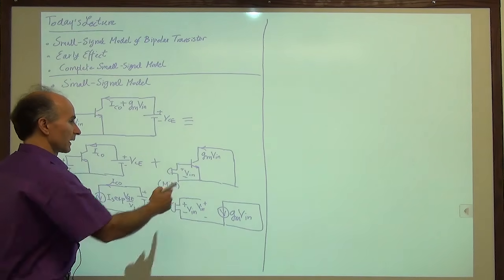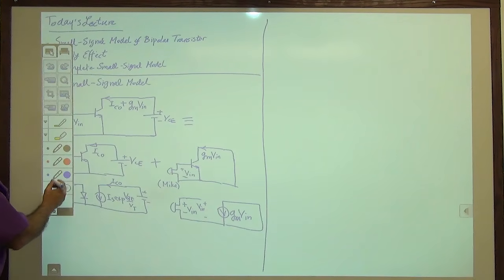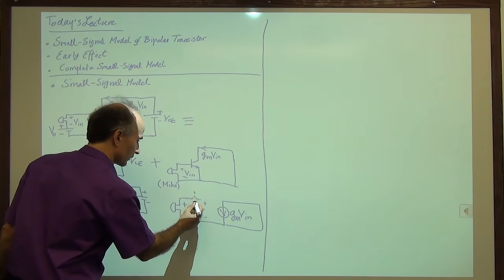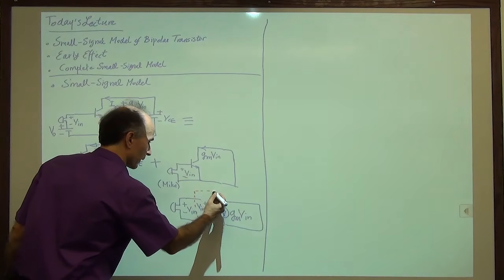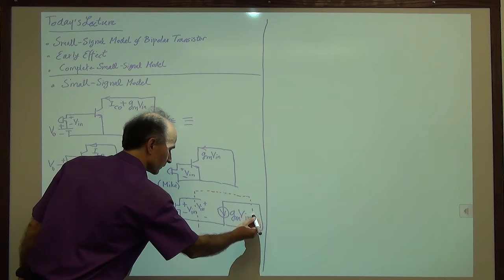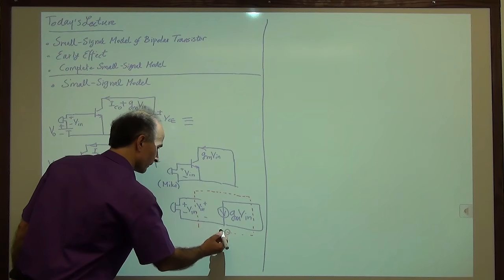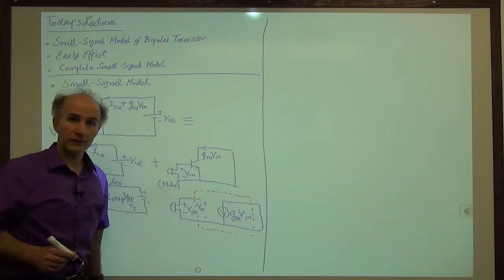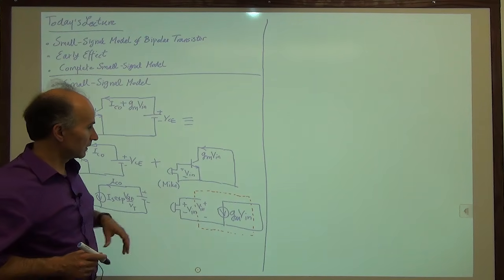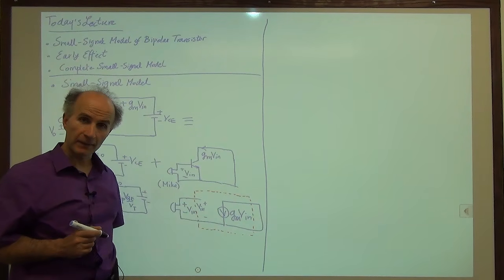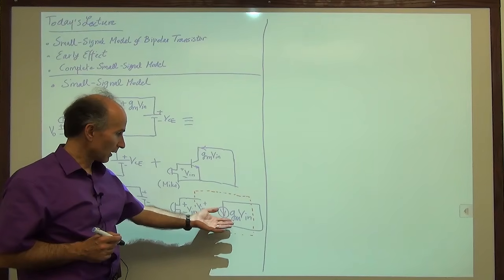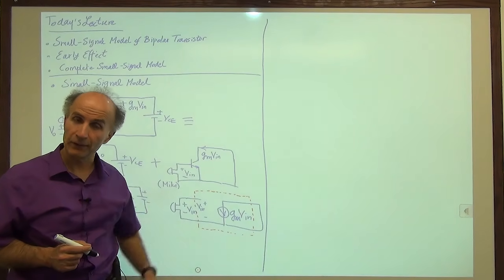Right? So all I did is try to replace this transistor with something that should make sense if we think about it carefully. So I'm trying to model the transistor by this dashed box. Okay, so lots of surprises here. Number one, we do not have an exponential dependence. It's Gm times Vin, Gm times this voltage, not exponential of Vin over Vt, etc., right?